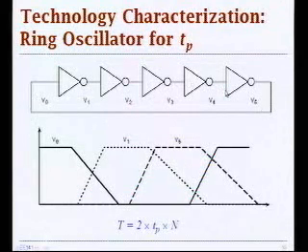And you typically have to have at least 5 stages for a ring oscillator to work correctly with the right waveform shapes. But normally you have maybe around 20 or so, but it has to be an even number. And so the total period for a signal to go between 2 rising or 2 falling transitions is given by this expression here. Period of oscillation is equal to 2 times the propagation delay, which is the average of low-high and high-low that we introduced in the previous slide.